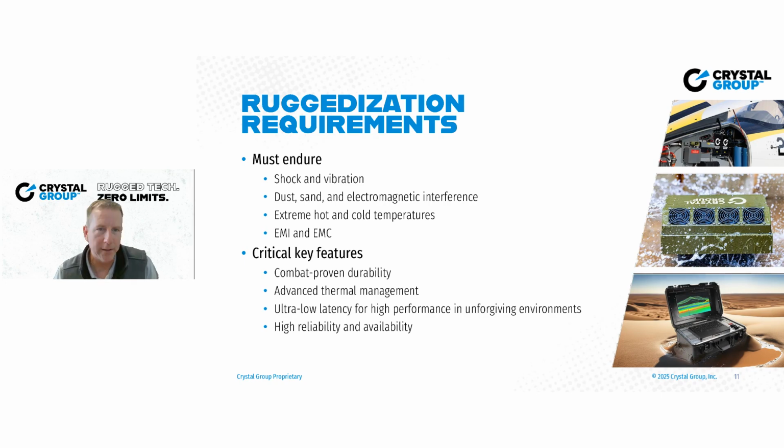When you're thinking in ruggedization or environment, think about what really is the shock and the vibe that you're going to have to experience. Think about the environment in terms of, is it dust, is it sand, salt, fog, EMI, EMC. Be thinking about your temperatures, whether you're storage, cold storage, hot storage, operational, short-term operational, that kind of thing.